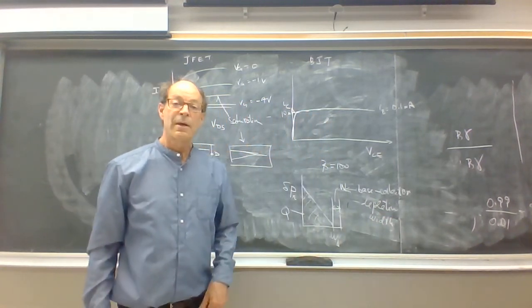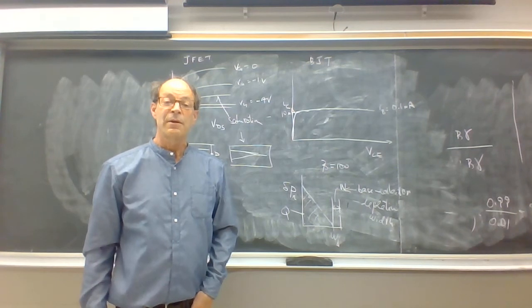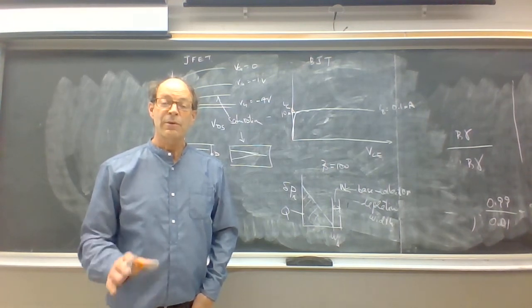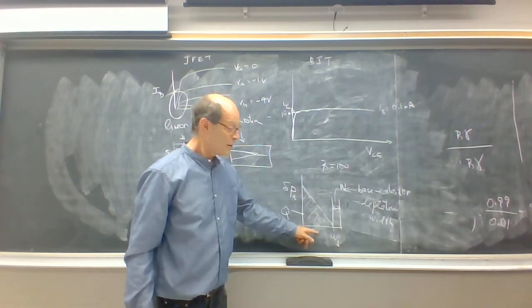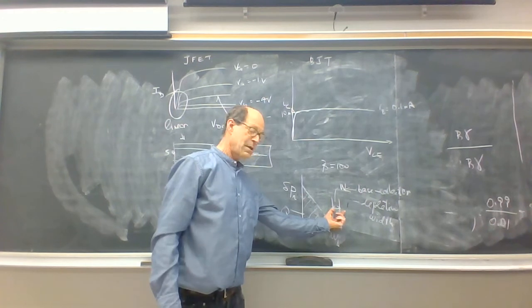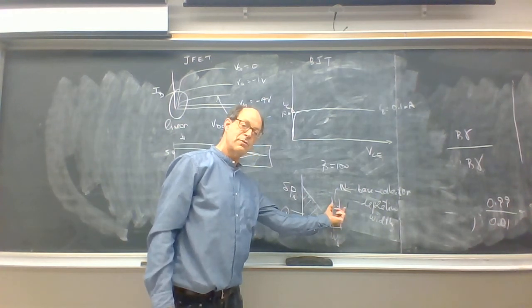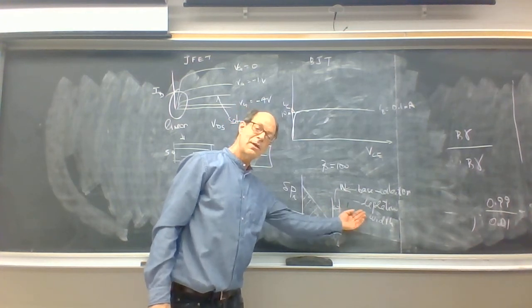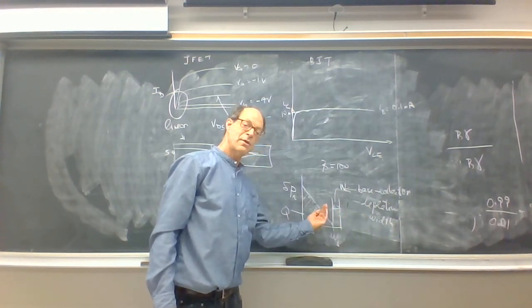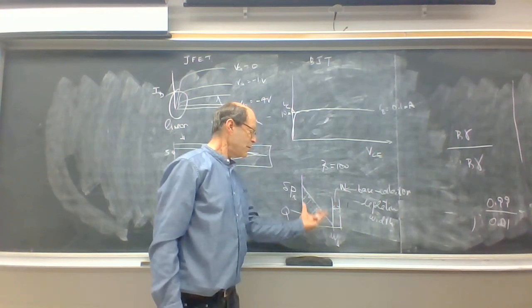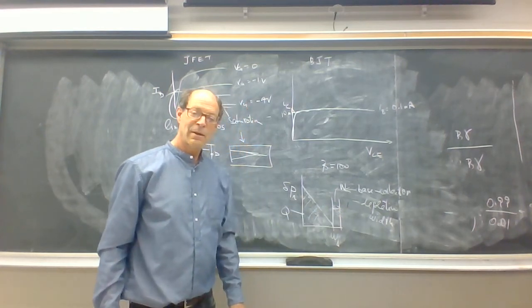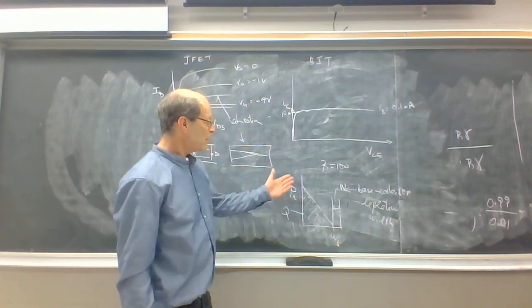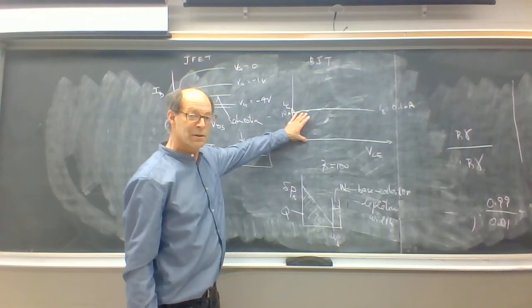But nevertheless, I won't significantly change the depletion width. I won't significantly change the conditions in the base as I change the collector emitter, the base collector depletion width. The assumption is that depletion width mostly extends into the collector and doesn't extend so much into the base. So the base width is relatively insensitive to that collector base depletion width. So you can see why you end up with a saturation condition.